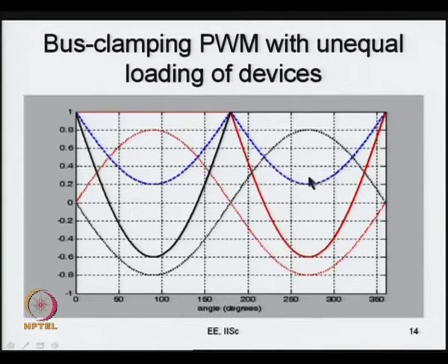Now, you see this blue signal, what is this blue signal? What is the frequency of this blue signal? Twice the modulation frequency. You see the red sinusoidal wave, that if you call it as 50 hertz, this blue is at 100 hertz now. You add this blue signal to both of this. How have I derived this blue signal in the first place? I have subtracted 1 minus the red phase sign to get the blue signal here.